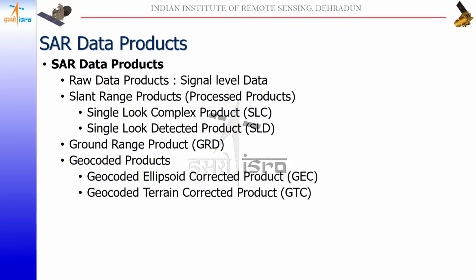So in interferometry, if we want to study deformation or any deformation study, then this phase information is quite useful. So for doing that application, we should use the single look complex SLC image.